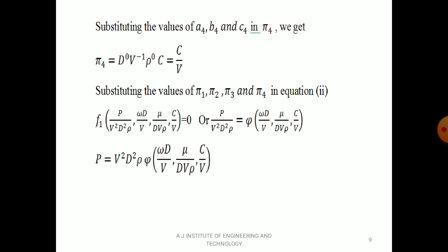So this is the expression for thrust developed by a propeller. Here, don't get confused. Thrust is related to force, it is not a power. So you have to be careful while writing dimensions for thrust. You have to write dimensions of force itself, that is F equal to ma. M unit is kg, a unit is meter into s to the power minus 2. So the dimension becomes MLT to the power minus 2.